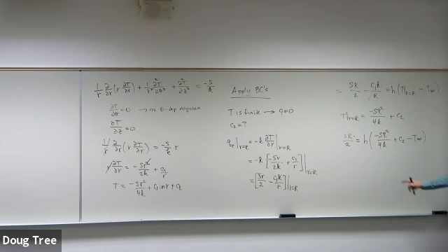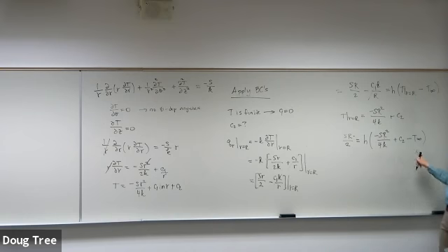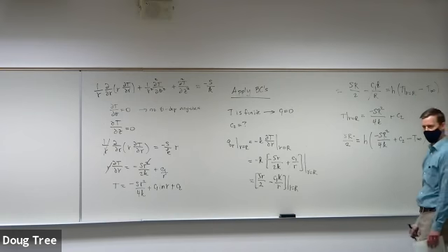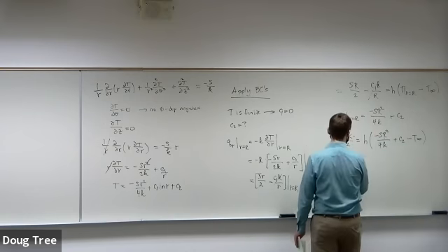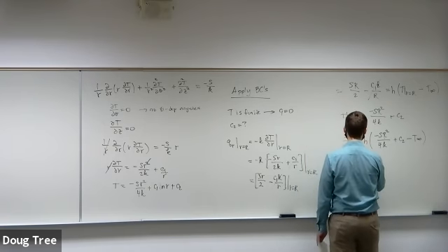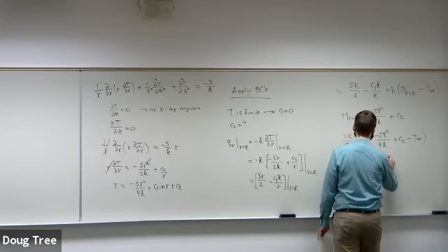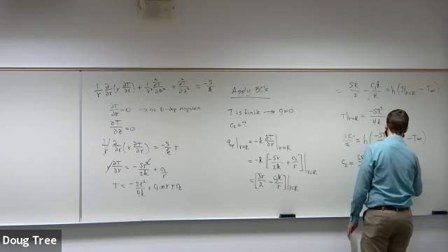So I should be able to just divide by H, move all the other stuff over, and I should find C2. So let's do that. If I do it in my head, I get C2 is equal to SR divided by 2H plus SR squared divided by 4K plus T infinity.